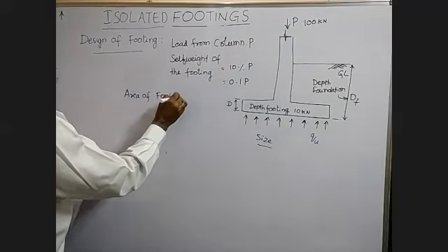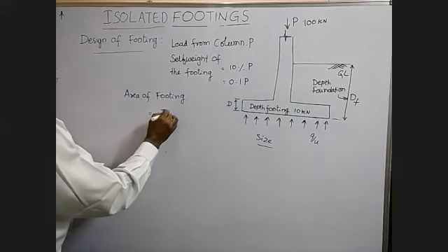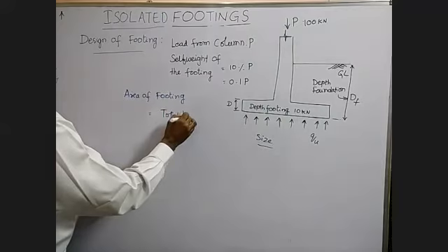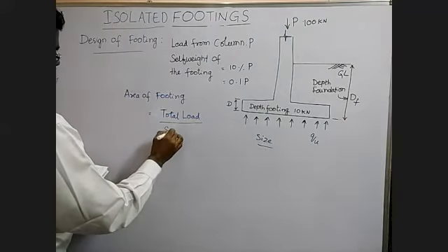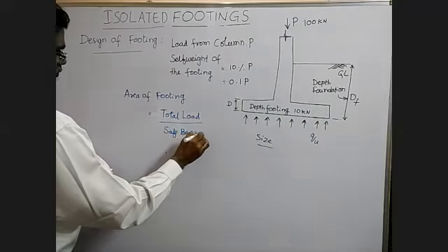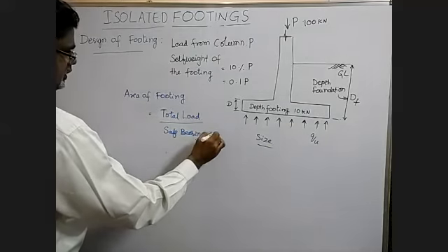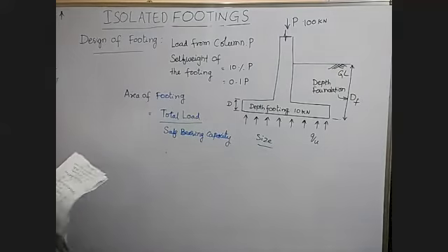Area of footing is equal to total load by safe bearing capacity, SBC. I think you might have studied this in soil mechanics or geotechnical engineering.